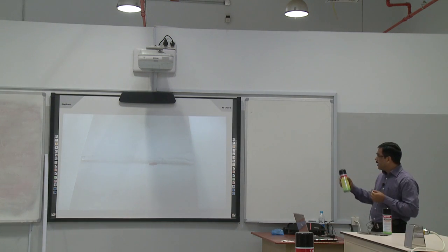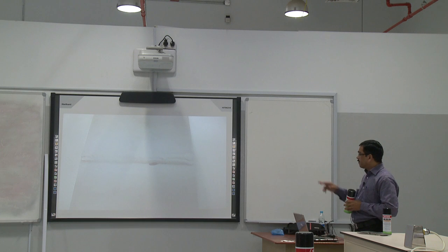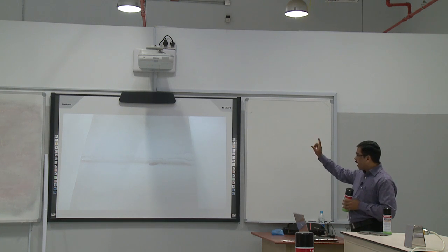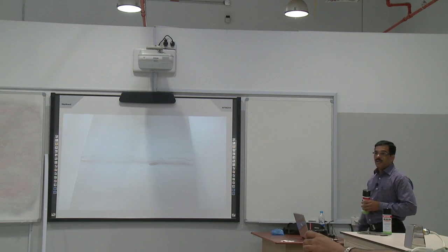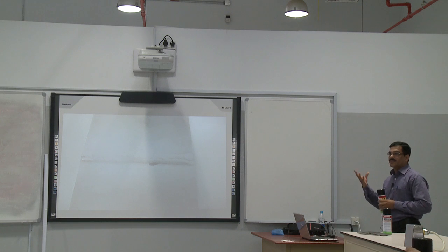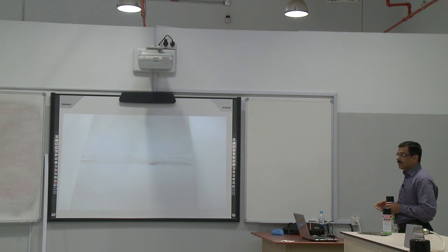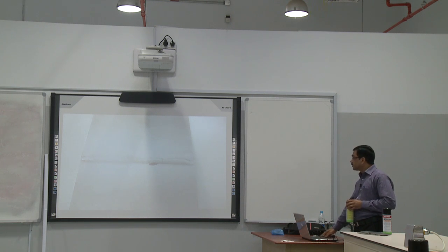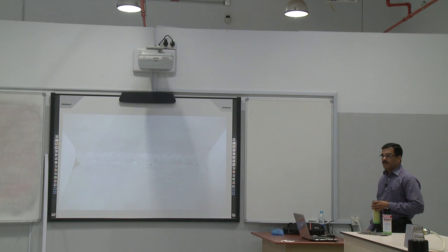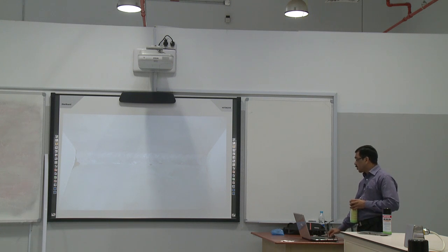This is just an example of an indication. After removing everything and applying the developer, there is some leakage of the penetrant coming out. So that indicates some indications. There are some indications here. Same like minor leakage, it's showing pores, so maybe porosity.